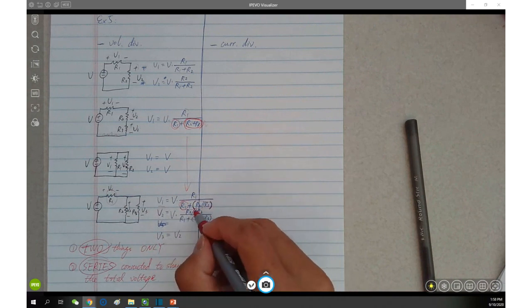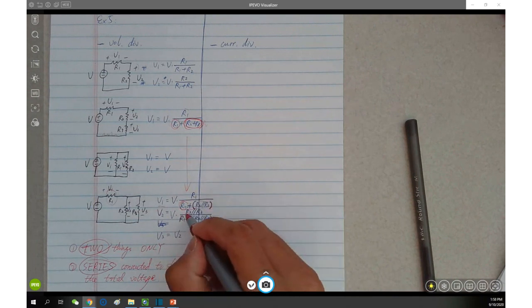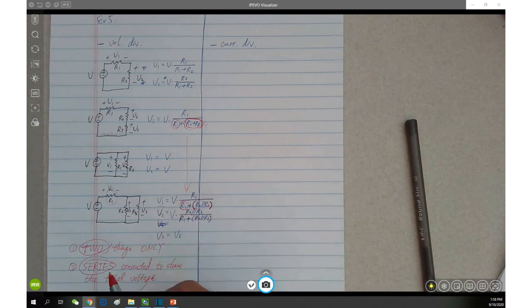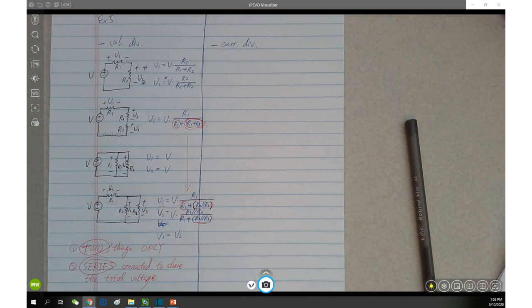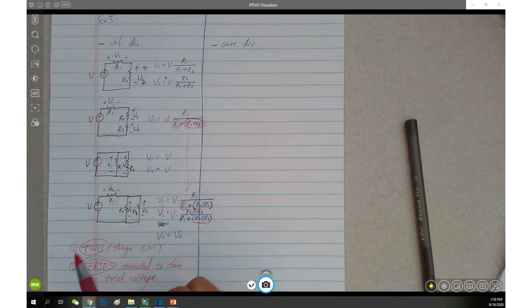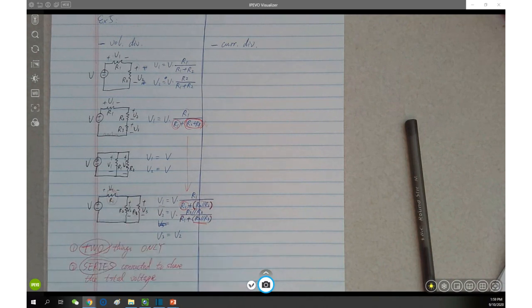In the numerator, well, in the denominator is R1 series with the combination of R2 and R3 in parallel. Okay. Because R1, there's no way to combine with anyone else. Doesn't make sense. Because R1 here is series connected with this parallel. You can't easily combine R1 and R2. No. You can't do that kind of combine. You can only combine R2 and R3. And then the result is a parallel resistor here, series connected with R1. Right?